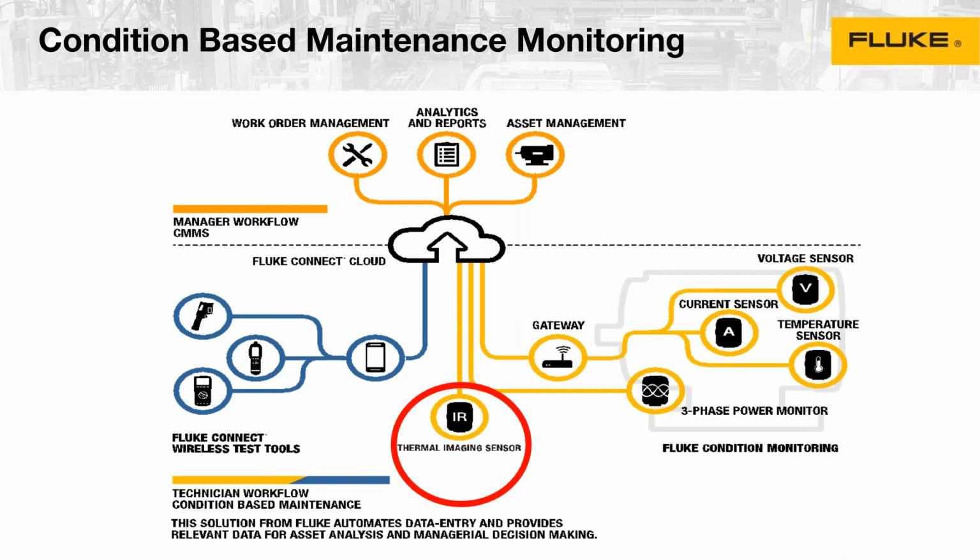And so at some point they're going to say, hey, we have these 3 pieces of equipment that we really need to monitor over the long term. And when I say long term, it's not just hours. It could be days, weeks, or sometimes even months. So in order to do this, there's only one way to do it. It's with a sensor that is wirelessly sending the data, but is always mounted at the same location, looking at the same center point on the asset.